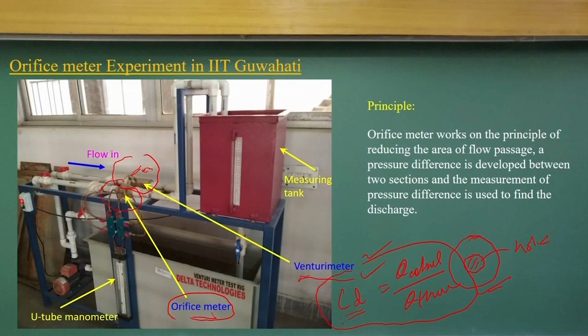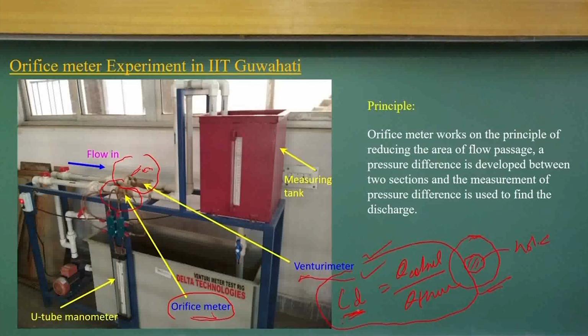So, these are gross representations of change of the flow patterns, the pressure and velocity patterns and flow structures. We do not look very microscopically at how it is changing, but it is a gross representation. We just look at the coefficient of discharge as the relationship between the theoretical and the actual.